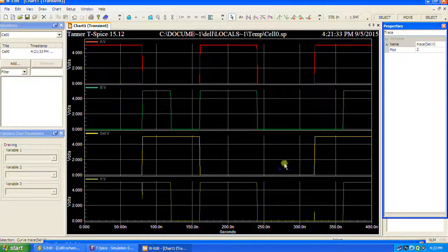This verifies the timing diagrams of the 2:1 MUX. Here there is provision to find the minimums, maximums, the markers. We will be needing this in the transfer characteristics of the inverter, so that if you want to perform any analysis, we can take the points from these.